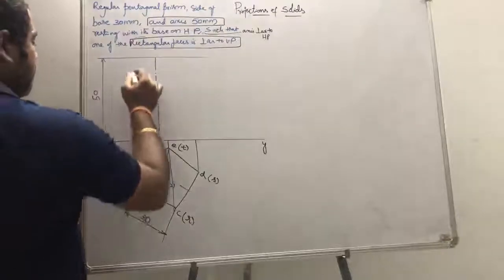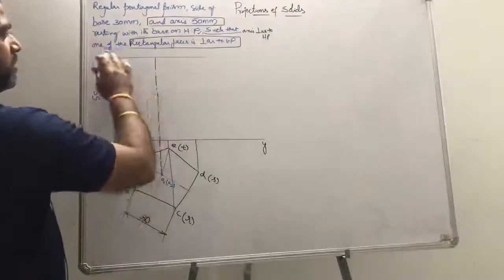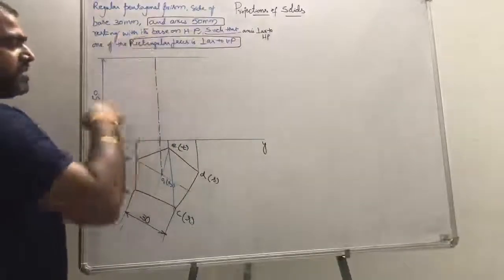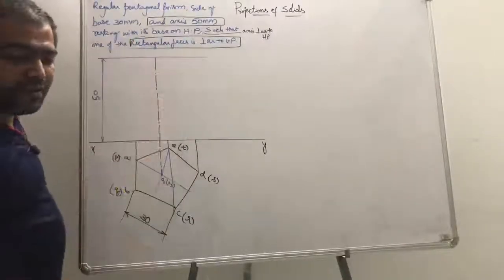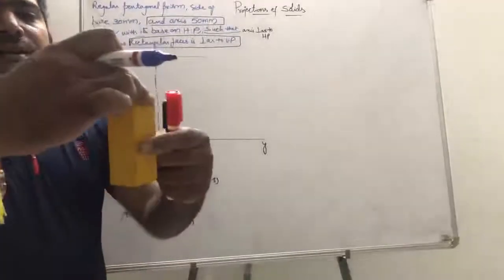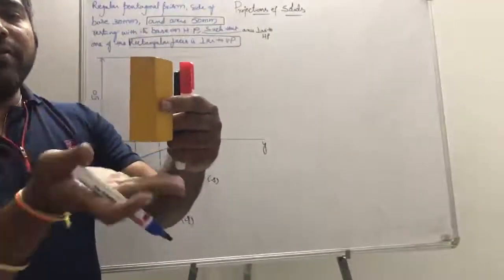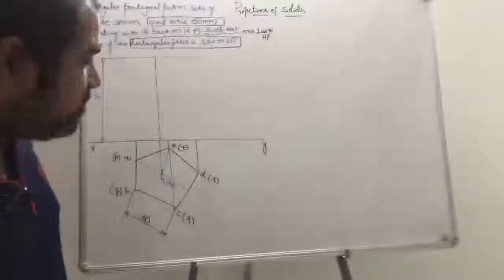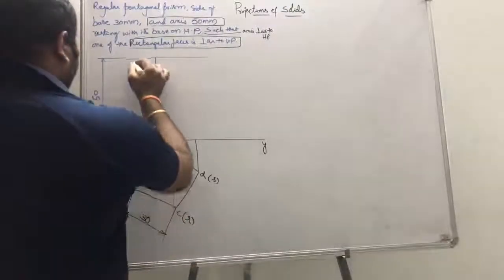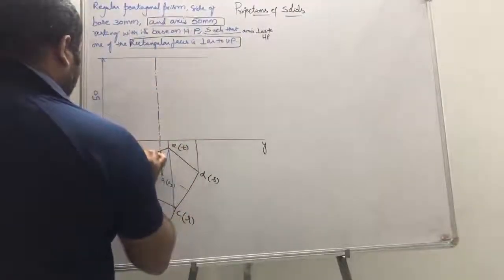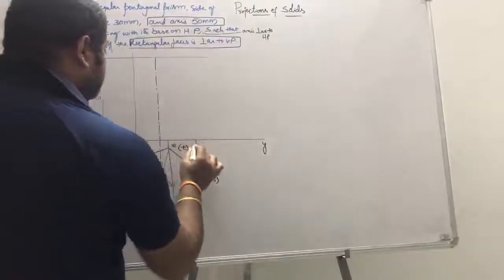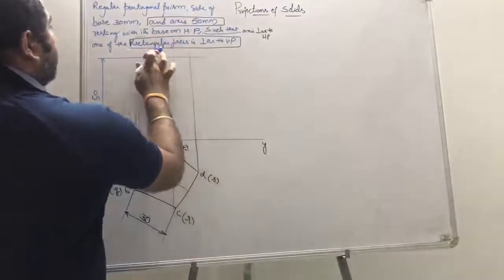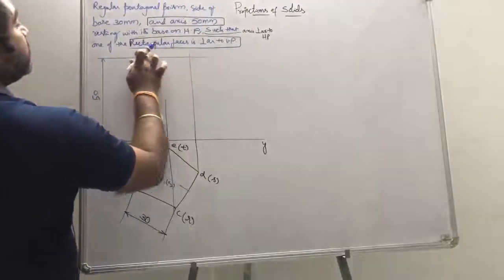Okay. And now extend the projectors up to this. This was the top base, this was the bottom base. So for a prism, I have two bases. While you are going to see from the front, let us see. When you are going to see from the front, you have bottom base, top base. So simply I just extend these projectors. Okay, and erase the excess portion.